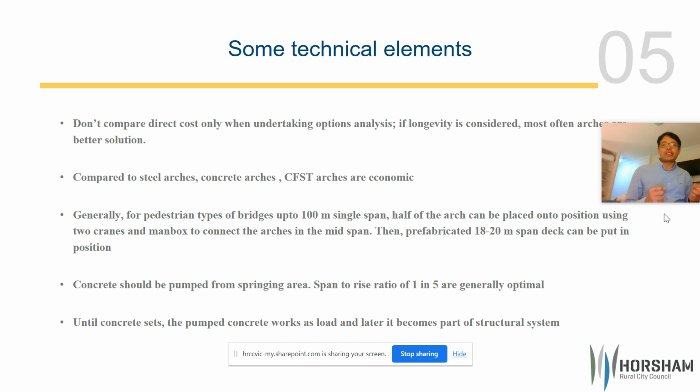It is not fair for arch bridges, because they may cost a bit higher, but actually they last longer. The maintenance cost is low. So you have to consider these aspects. If you analyze that, most of the time you'll come to the conclusion that arches are better.